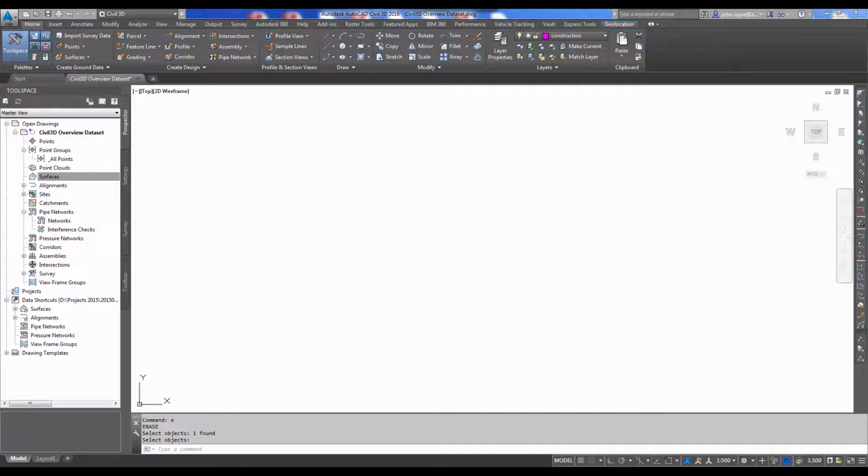So let's start to establish some existing conditions. There are a couple different levels of existing conditions that we'll talk about. One being more of a preliminary look, so we'll use GIS data to look at those existing conditions. And the other one would consist of a detailed survey where we had a survey crew actually go out and pick up field to finish line work.